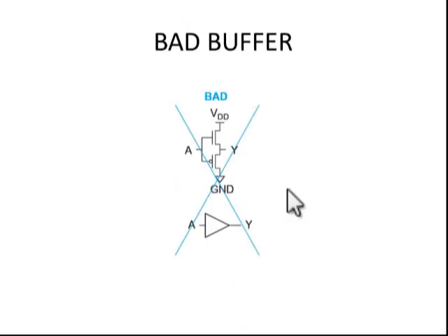So now we will see what is the need of CMOS logic. Actually, the main problem in the PTL logic and transmission gate logic is when the condition is satisfied, we are getting the correct output. Suppose if the condition is not satisfied, that means if there is no path for the output from the input, the output won't be zero.